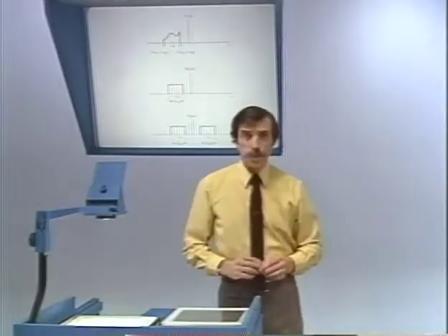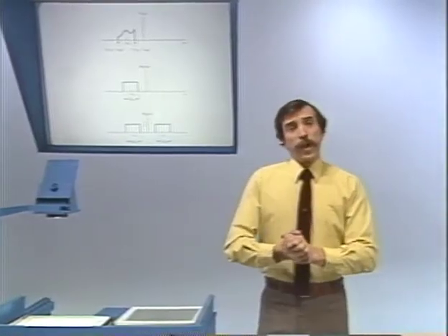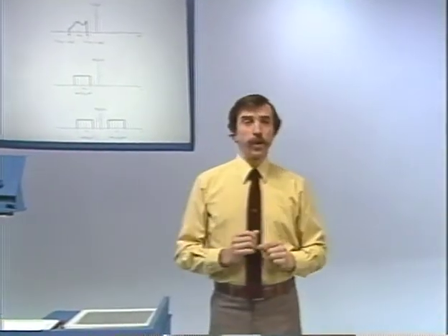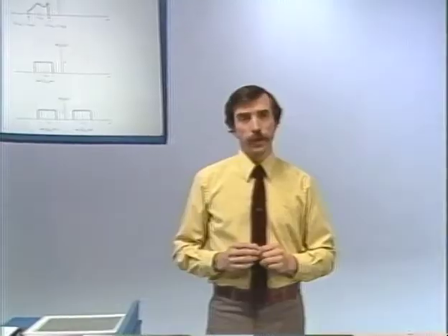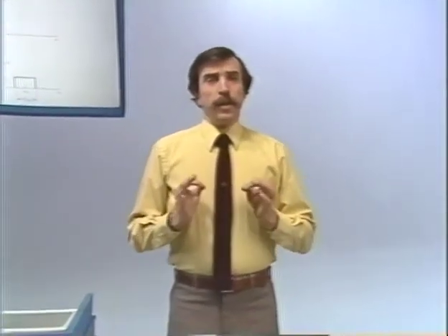Now, just to reiterate a point that I made earlier, the question, of course, is why would you go to this trouble? Why not just build a bandpass filter? One of the reasons is that it's often much easier to build a fixed filter, a filter with a fixed center frequency, for example, a low-pass filter, than it is to build a filter that has variable components in it so that when you vary them, the filter center frequency shifts around.